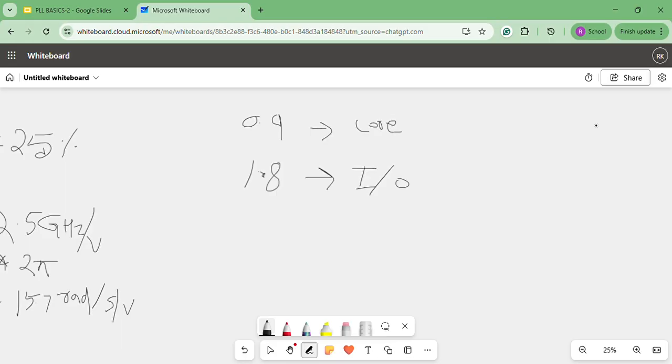Okay, so basically we will design our charge pump and PFD with, mostly we'll design our charge pump. Here I have told we are designing with 0.8, but we will design our charge pump with the IO supply. Sorry, the charge pump with this IO supply. Why? Because this is a more stable voltage which is coming from BGR, and the internal voltage has shaking, which will have a shaking effect and may change our frequency. But this is a stable DC voltage which is directly coming from the PMU block.